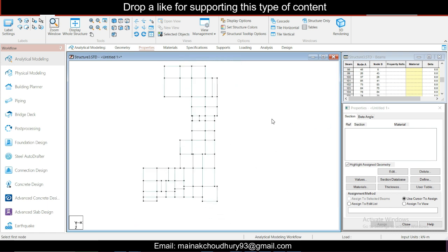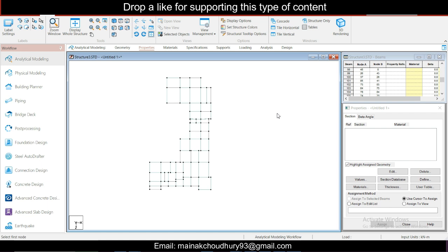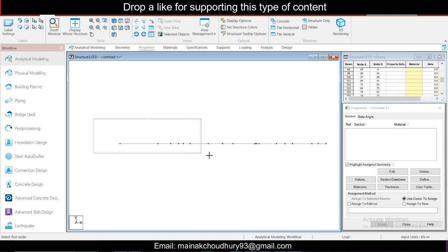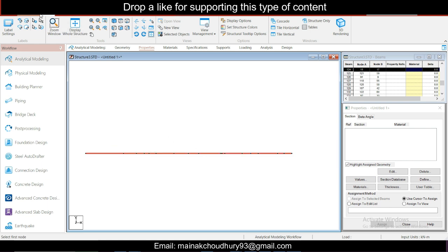Now next we can do the next floor, which will be the translation repeat option. Okay. So we will go to view. Or simply you can just select the column nodes and then we can do link steps and then translation repeat, but actually we need to copy the entire floor because we need to copy the intersections as well. So we'll go to view and we'll go to front view, and we cannot use link steps because there are other intersections as well, and we'll use the option of geometry.